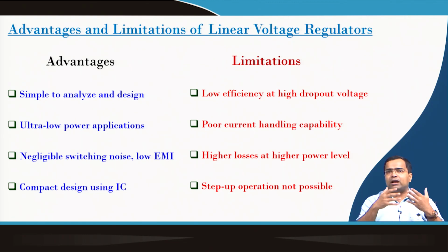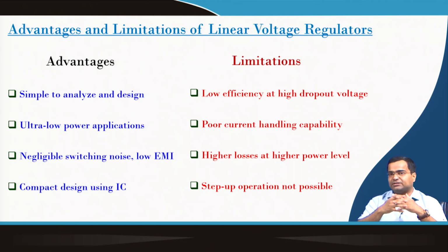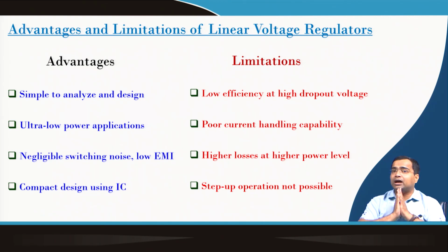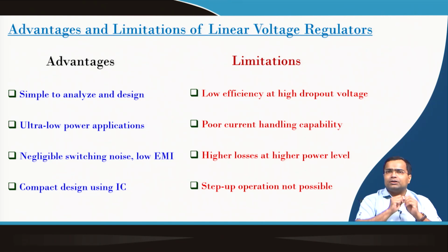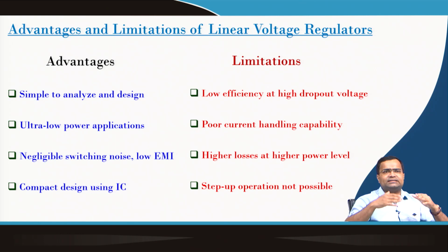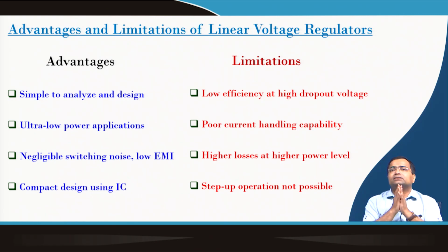It also has poor power handling, current handling capacity, because as I said, if we try to use it for higher current, then the losses will be significantly higher and it will be unmanageable. It is also very lossy at high power level. That means, if the load current varies, and it is designed for a certain load range, it is good to use at lower current level. As the current level increases, the losses increase.